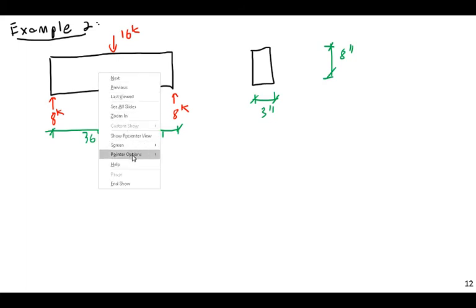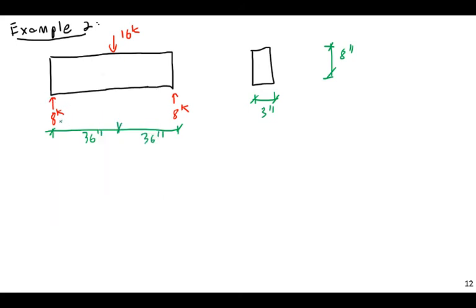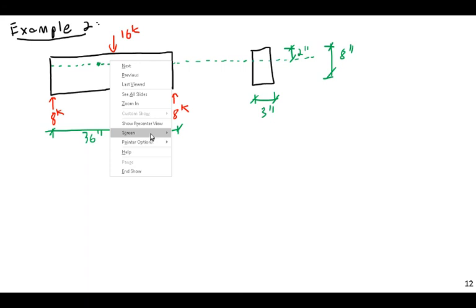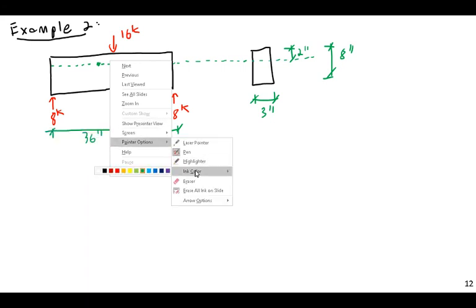However, I am interested in not the cross-section itself, but the shear stress at 3 locations. Let me draw this by 3 lines. First, I already have this pen up, so let me do the B line. Line B is going to be located 2 inches from the top. Line A is going to be located at the neutral axis, 4 inches from the top.